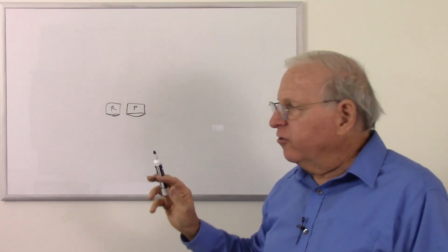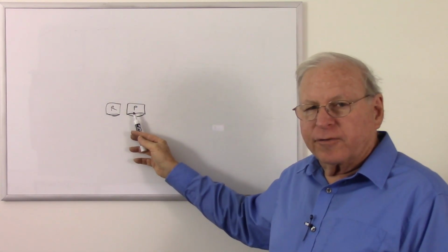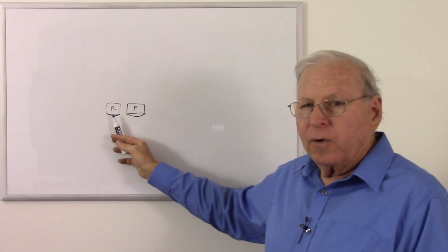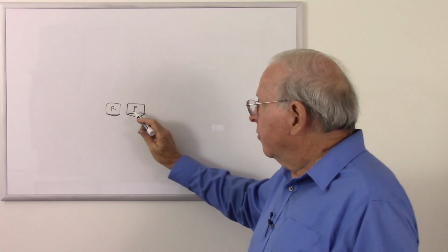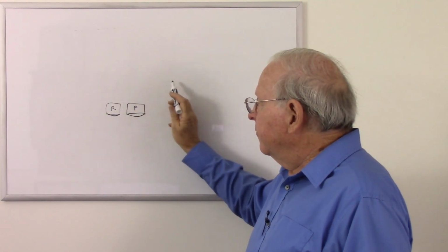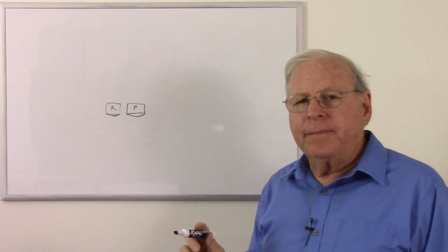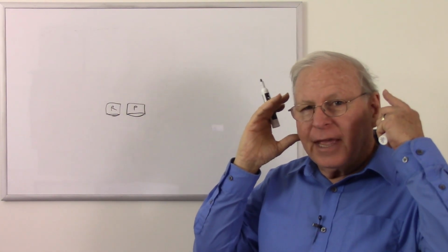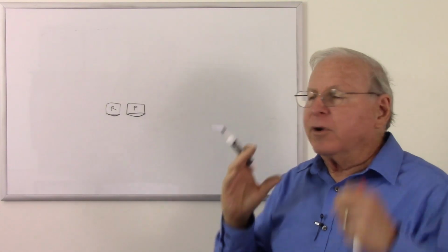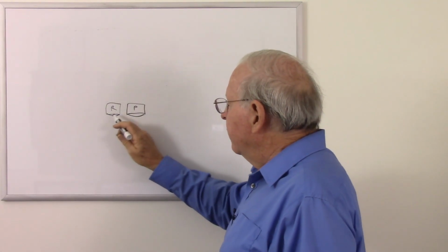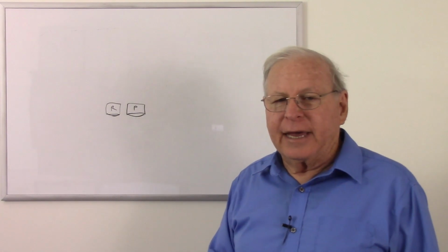Two advantages to this. One, this one's optimized for playback, this one's optimized for record. Also, you could monitor your tape as you recorded it, so you could actually have your sound come out of the playback as you were recording, and so you could have headphones on, and there's a slight delay, but you could hear if there were problems in real time. So that was another advantage of separate record and playback heads.